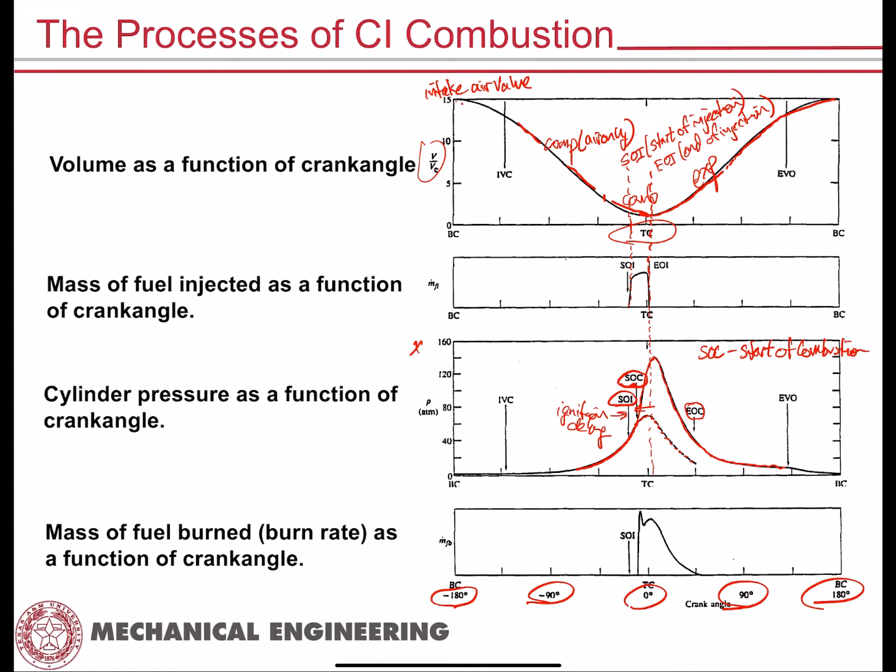And just to segue us into the next set of slides, we have our fuel injection profile, which is what this curve is profiling here. This m dot f sub i is the mass of fuel injected. You can see that when you have start of injection, your mass of fuel injected rises, and it continues to rise until eventually you say, okay, it's time to end injection. So then you start to close the fuel needle valve, right? As that needle valve closes, the mass of fuel that's introduced into the cylinder decreases and eventually gets to zero.